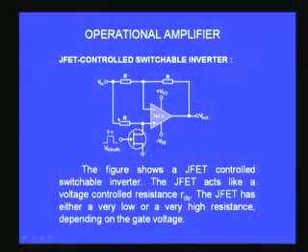So you can see in the circuit which is shown on the screen, you find this symbol. I am sure you are able to recognize this is the junction field effect transistor, and I give a pulse here. So the pulse is from 0 to 6 volts. When it goes from 0 to 6 volts, when it is positive, this FET will be conducting, and when it is ground, it will be not conducting.